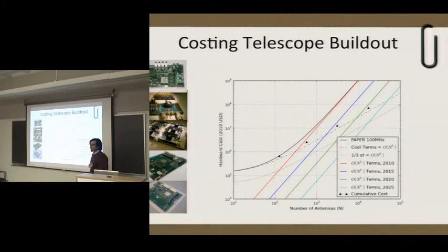I think another one of the truths looking forward in radio astronomy is that, with capabilities doubling every 18 months or so, you find yourself wanting to balance the need to get science done now. So you have costs of your telescope, and you'd like to build as big an array as you could. So you want to build lots of antennas, but then there's the cost of correlating them: you have to pair every antenna with every other antenna, so it goes as the square of the number of antennas. On a log-log plot, I've drawn costing curves for the PAPER telescope, where we have the contribution of the N squared term, which is all the pairs of antennas, compared to the N term, which is just the cost of metal, of amplifier chains, and some of the processing that goes linearly with each antenna element.